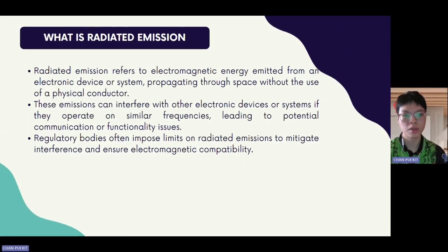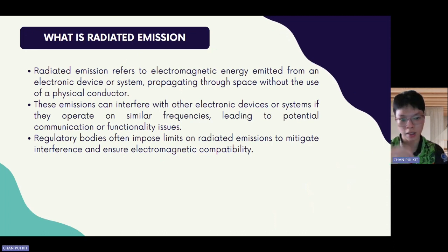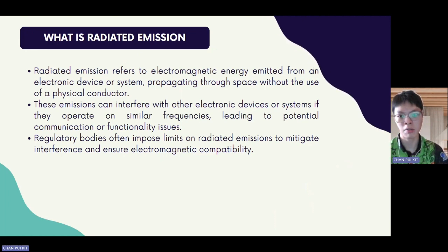Radiated emissions refers to electromagnetic energy emitted from an electronic device or system, propagating through space without the use of a physical conductor. These emissions can interfere with other electronic devices or systems if they operate on similar frequencies, leading to potential communication and functionality issues. Regulatory bodies often impose limits on radiated emissions to mitigate interference and ensure electromagnetic compatibility.